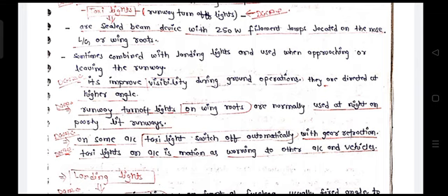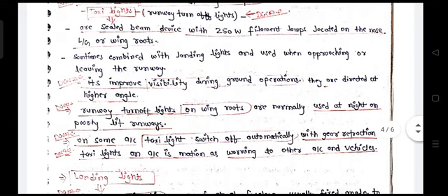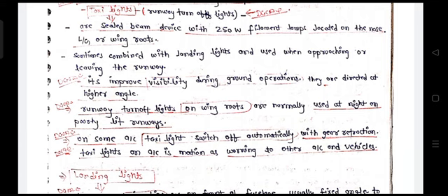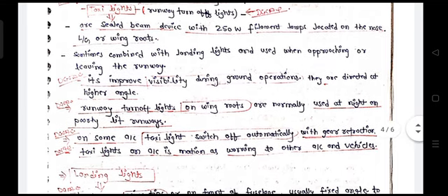When you are landing or taking off, during that condition in the runway strip, you do not require that light. You only require it while you are taxiing to the runway, or after you have landed and are going through the taxi, then you switch it on. Just after completing the taxiing, when you have reached the runway and are going for the takeoff roll, before that you switch it off. That's the reason it is called runway turn off light. It means in the runway it will not be operated. In the runway only the landing light will be on, before landing or before takeoff.